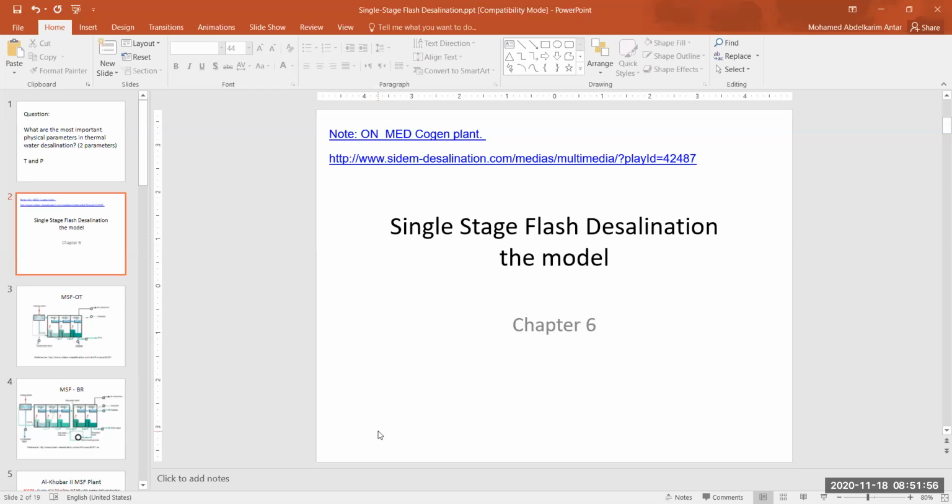I did not mention the idea that we have done with the MSF system, which was basically to connect a thermal vapor compression unit. But it has some more details that need to be done, but that was basically the idea. Attach a TVC and select the best location where the TVC is going to be placed, and then do some adjustments in terms of flow rates, and then you can get some sort of better productivity.